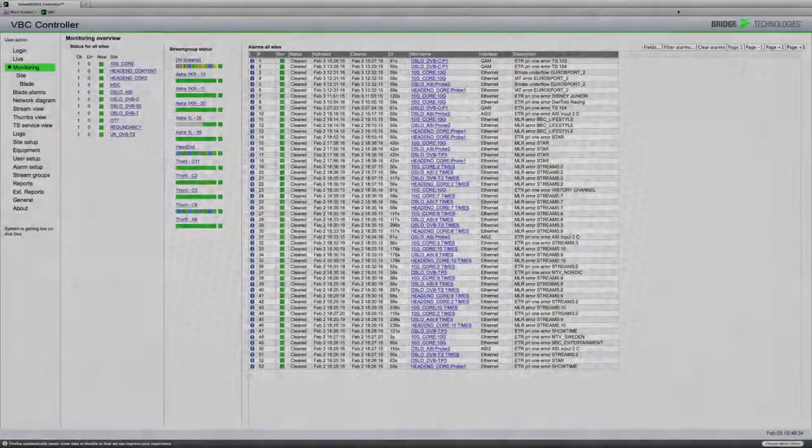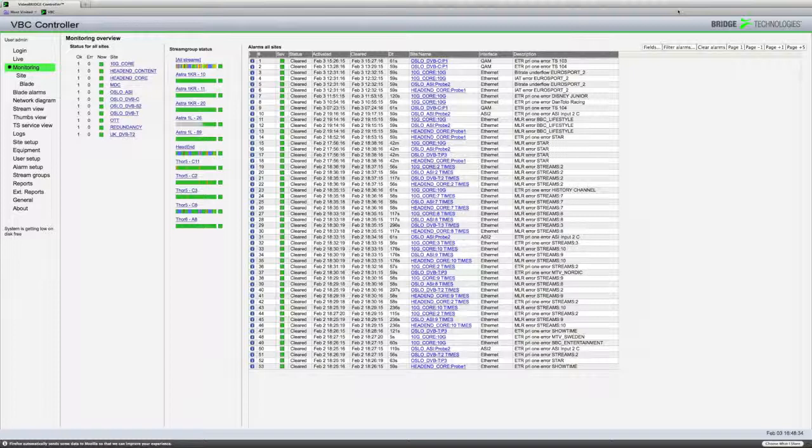In this video, we're going to look closely at the MicroETR tool that's available in all probes that have one or more ETR engines licensed. The MicroETR is a patented tool that enables a large volume of ET290 data to be seen at a glance. All ET290 Priority 1, 2 and 3 errors are displayed, along with some selected other checks added by BridgeTech.